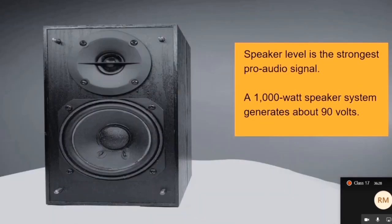So we'll come back to what we do about that right after I describe speaker level, which is the fourth, final, and largest of the four analog pro audio signals. Now, of course, this varies speaker system to speaker system. But imagine you're using a professional PA system, putting on a DJ show or a band show, with nice big speaker arrays, maybe a subwoofer, monitors, and power amplifiers generating something like 1,000 watts, maybe a couple power amplifiers. That's pushing about 90 volts.